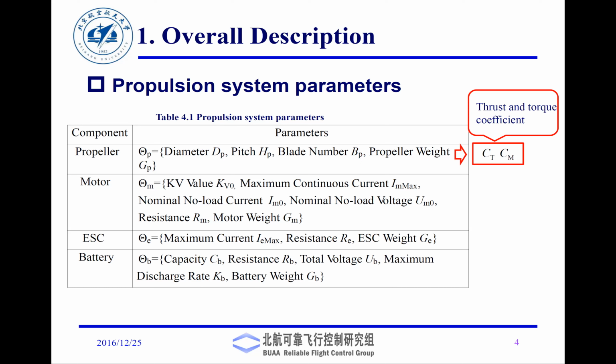Basically, that is the reason why aircraft, when they are taking off, need to have some speed so that the incoming air has enough velocity. Incoming air gives rise to dynamic pressure. Dynamic pressure multiplied by the coefficient of lift would give you the lift on the airplane.